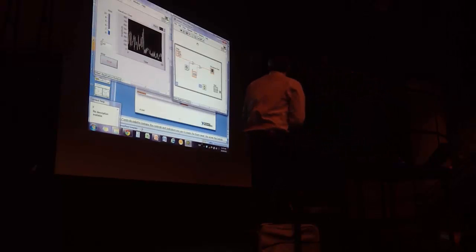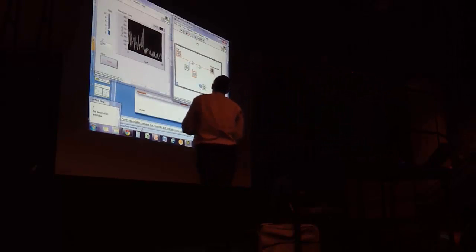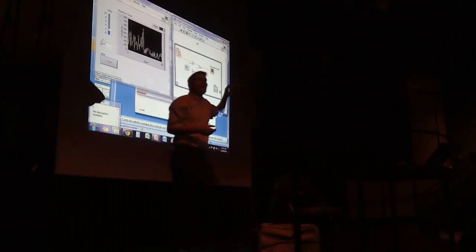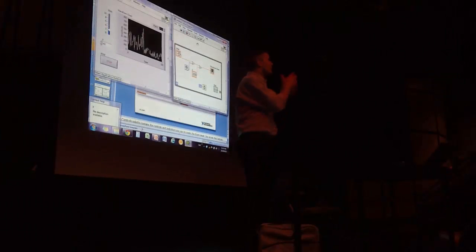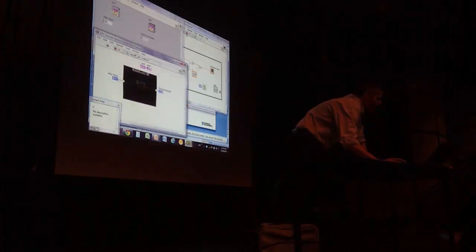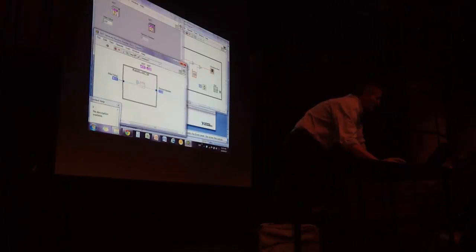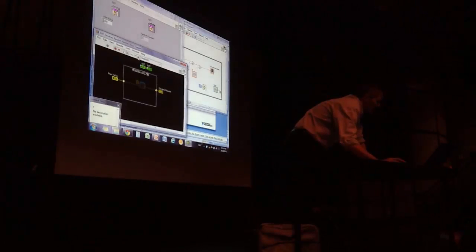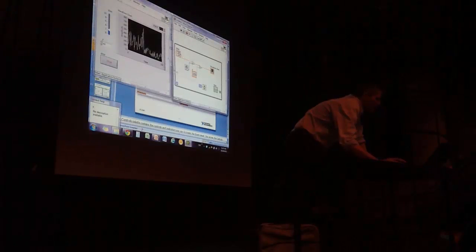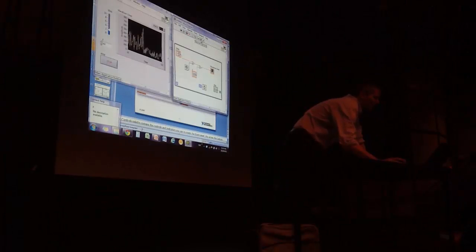I've paused the execution, so I have now the possibility to do single stepping through the application, where I say, okay, I want to go now to the next step and see what's happening here, and go inside what in this function is happening, and I can go out of this function again. So I can step into all these kinds of functions and just step through my program.